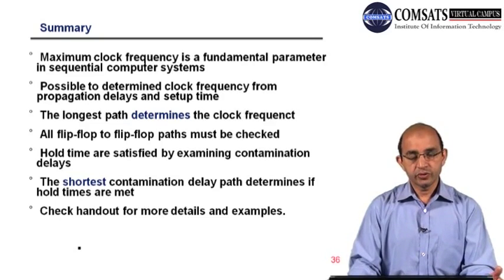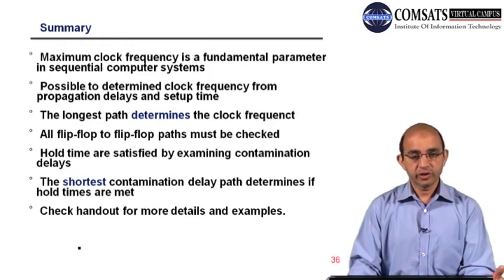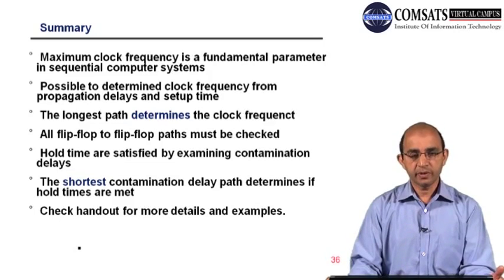Then we switched to sequential logic, which involves combinational logic and sequential logic. So we need to take into account all the parameters defined for combinational logic when we are analyzing the timings for the sequential circuitry. We defined some new parameters that include the setup time and the hold time for the sequential logic.